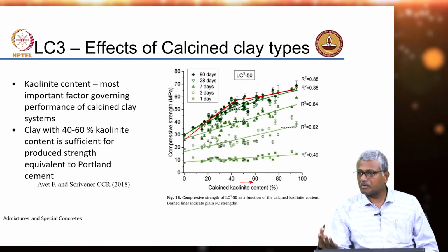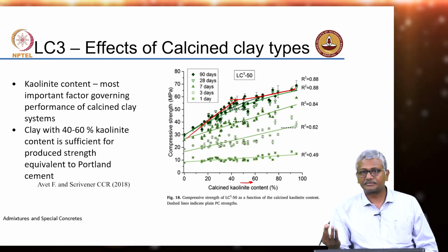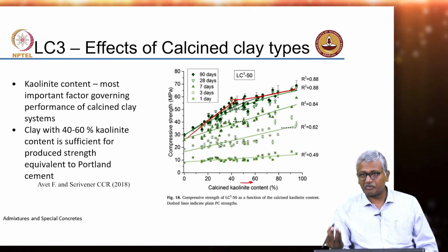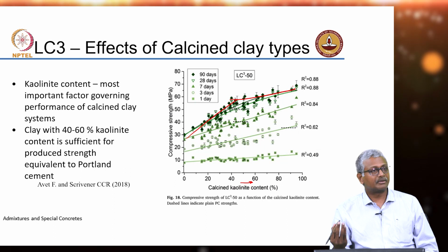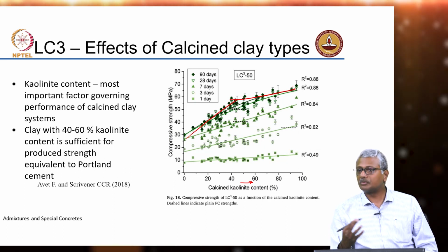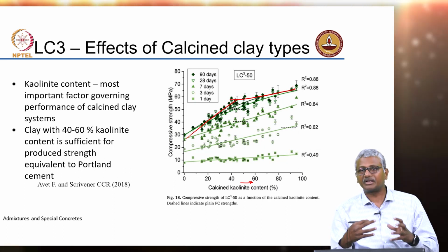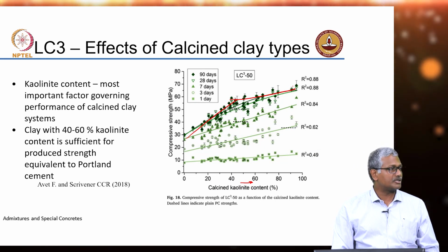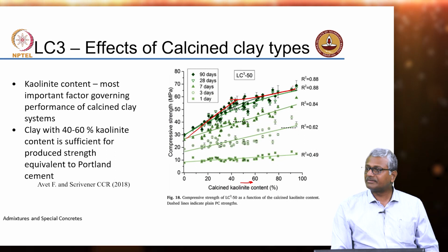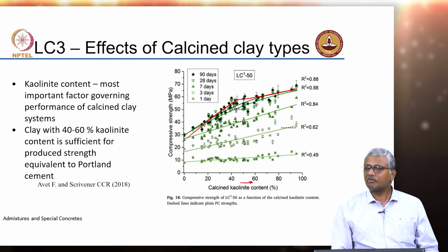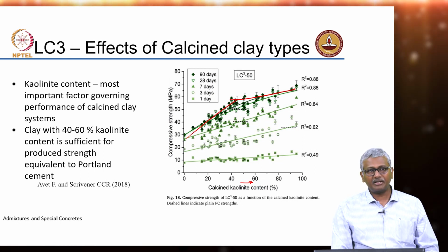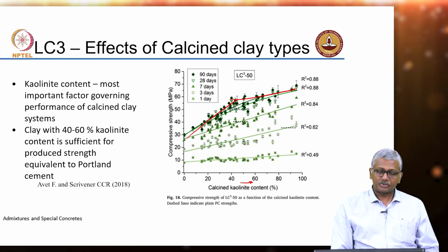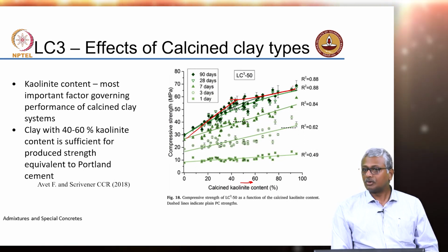Sometimes even quartz may be present in your system, right? Sometimes even calcite, calcium carbonate, may be present in your clay, which makes it more yellowish. When you burn such clays to make bricks, you get yellowish colored bricks. When you have the iron oxide rich clays, they give you the reddish bricks, right? So all of these go to show that there is a lot of material that can technically be utilized in the form of calcined clay, because so much of it is actually dumped and not utilized.